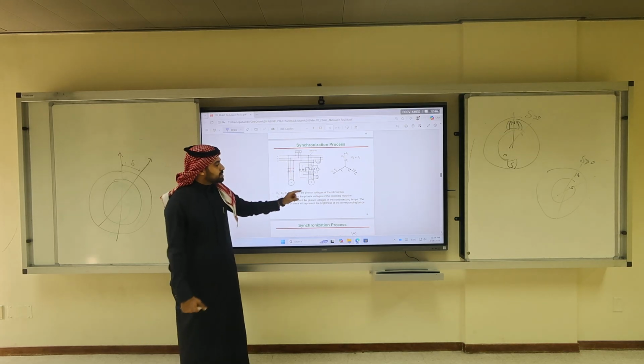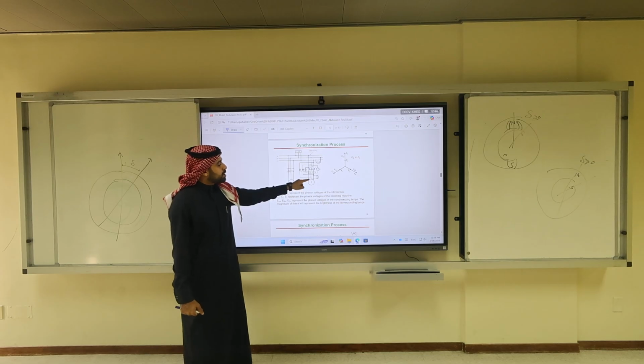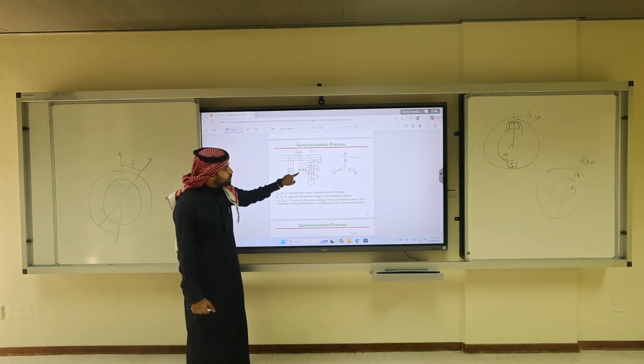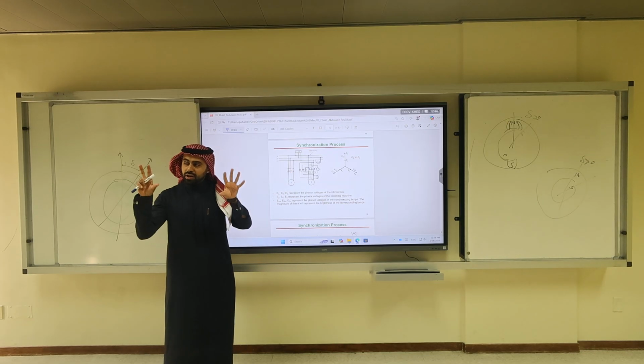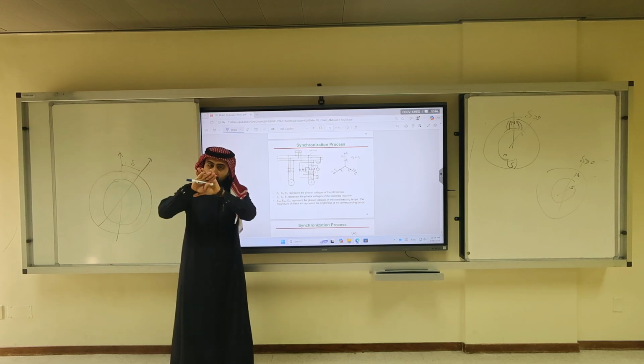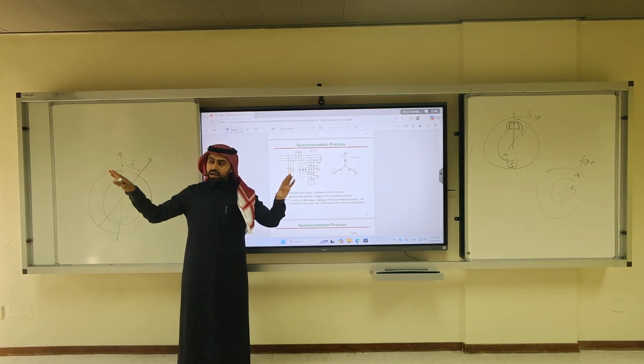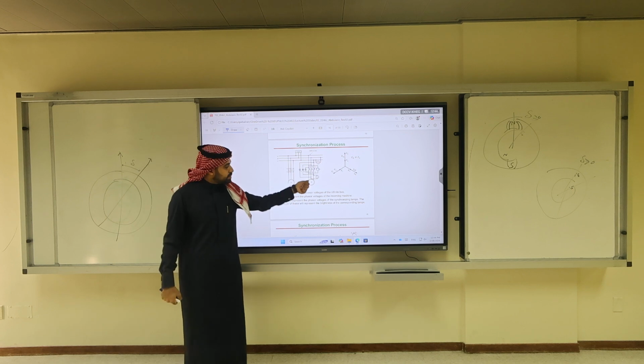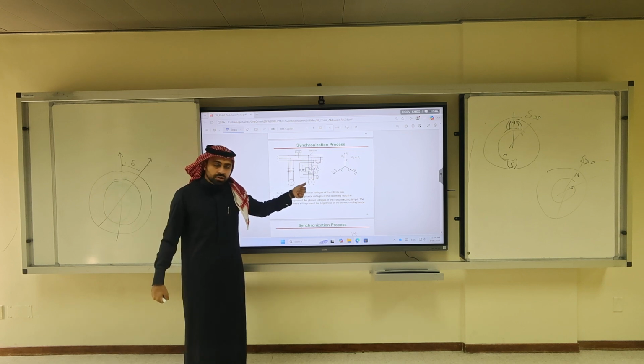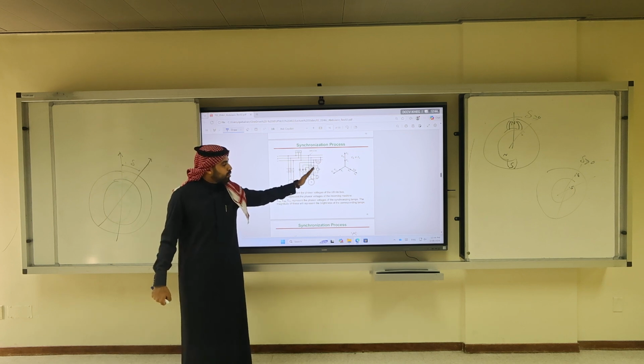Initially, without synchronization, there is a voltage drop, so all the light bulbs will be flickering. If all the light bulbs turn off, it means I am in synchronization mode and I can safely close all the breakers.